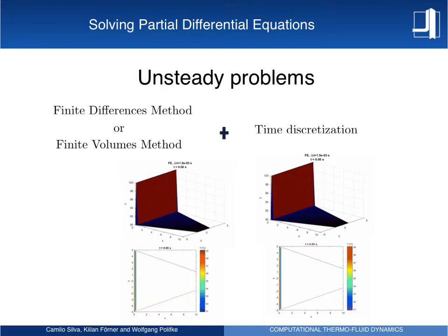And the interesting part here is when we talk about convergence. Maybe you have heard about this CFL condition and so on. We will also talk about this here and realize that if we have a right evaluated time step to discretize the time in our equation, everything is going to become as we wanted.